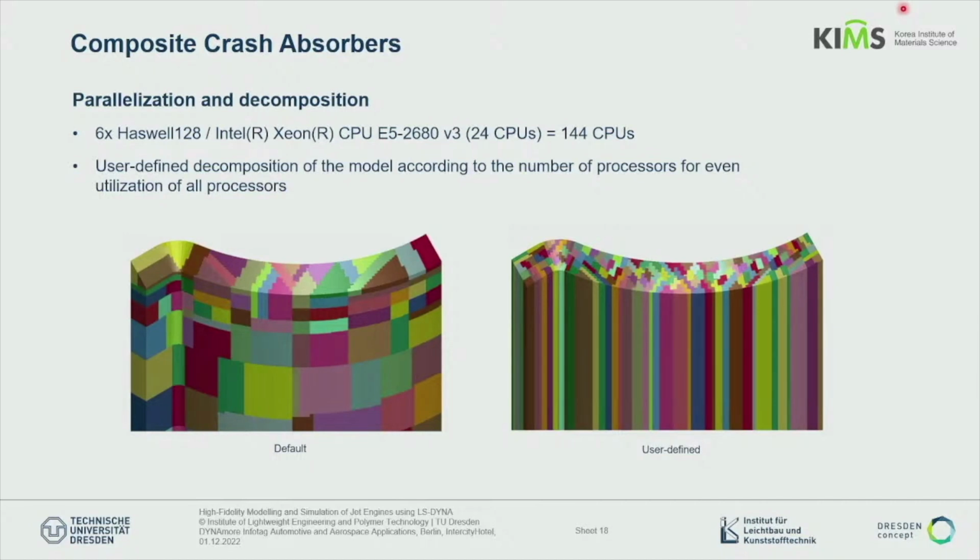So here we come to actually a computing task. We realized that it's very beneficial to do proper decomposition, especially in this loading case where we have a very localized phenomenon. It starts from the beginning in the impact contact area, so everything's happening there, and nothing is happening in the first couple of milliseconds in the lower part.